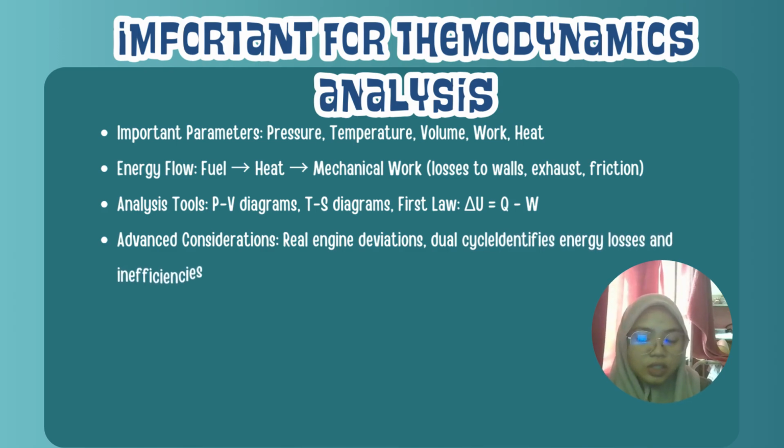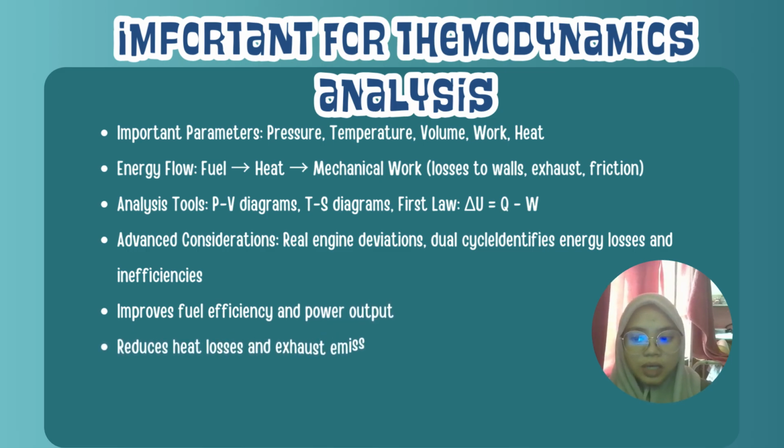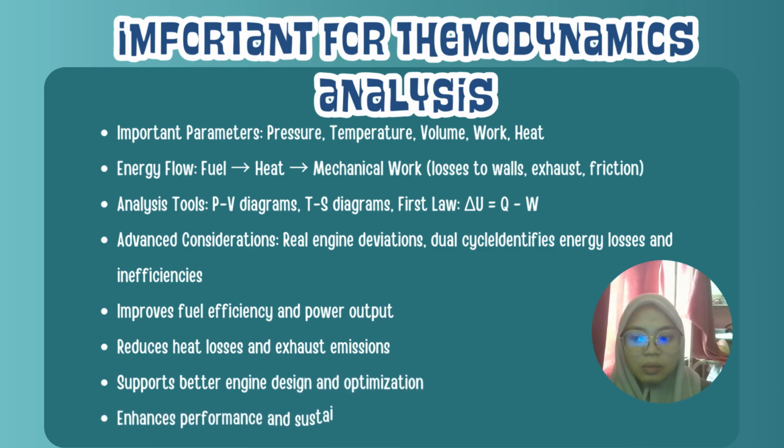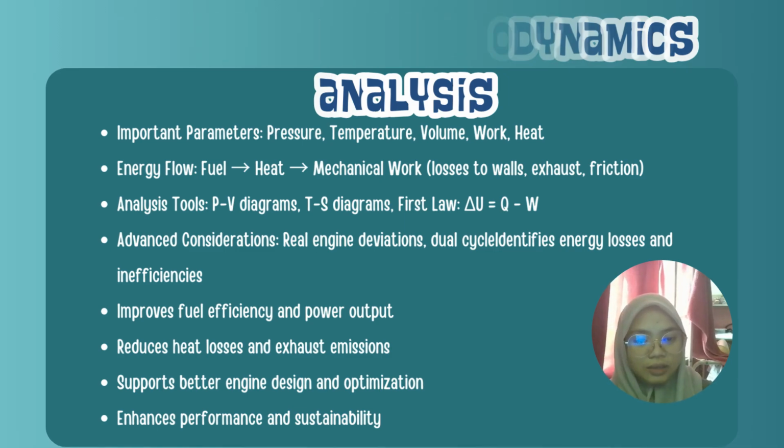Important parameters such as pressure, temperature, and volume change throughout the engine and need to be determined. The work produced by the engine is represented by the area under the pressure-volume diagram, while heat represents energy from the fuel or lost to the surroundings. By understanding thermodynamic cycles such as the Otto and diesel cycles, engineers can predict engine behavior, recognize efficiency limits, and also design better engines that operate more efficiently with lower emissions.